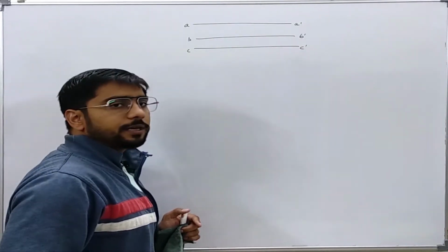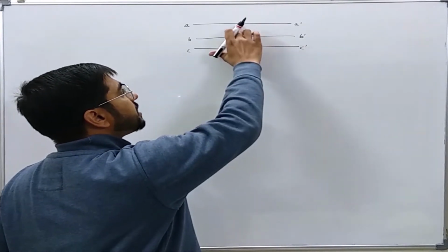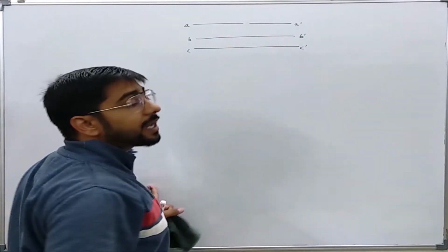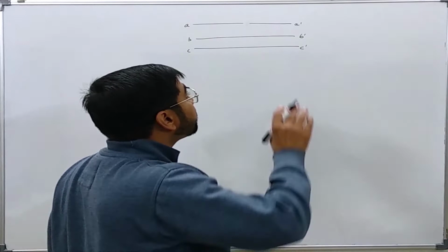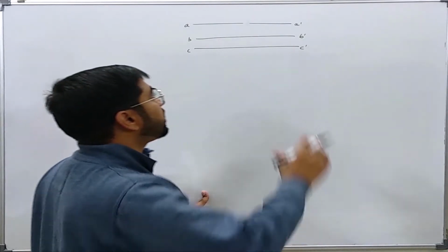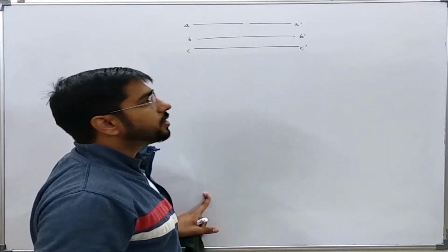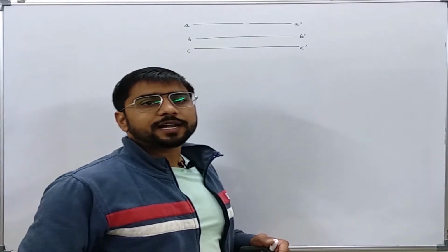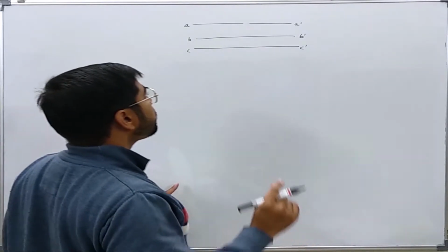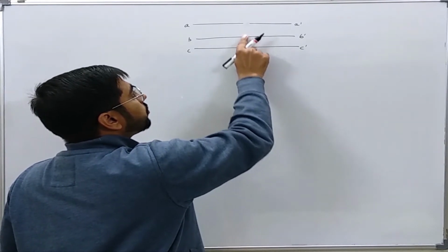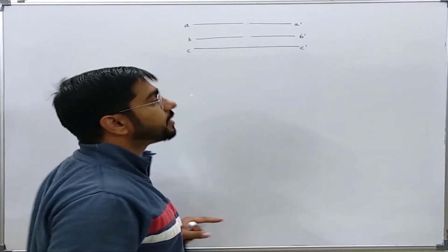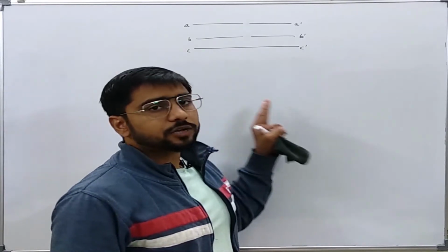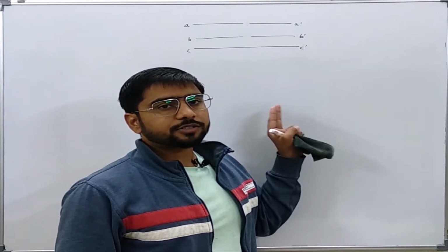Okay. Now, if there is, let us say, some fuse in the circuit and this fuse gets blown only in this phase, then again it creates some unsymmetry or unbalance in the system, which is clear that phase A is now open. So it indicates that we can analyze this kind of system using symmetrical components. Similarly, if there are two phases open, then again there is an unbalance in the system. We can easily analyze this kind of system also using sequence components or symmetrical components.